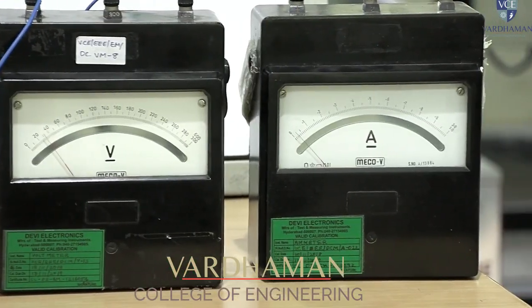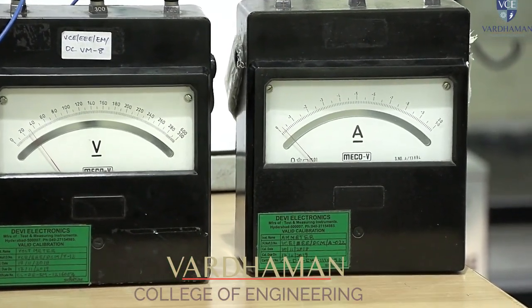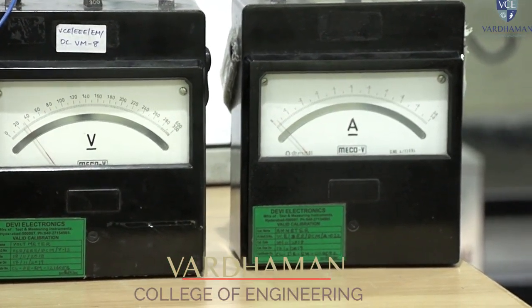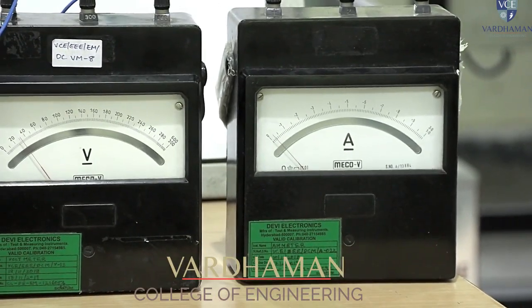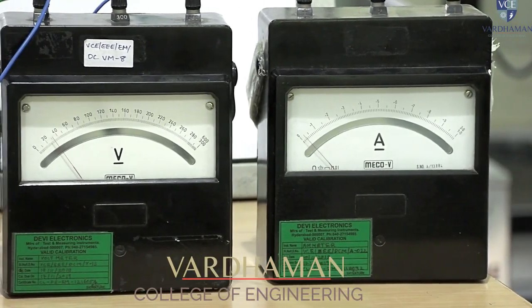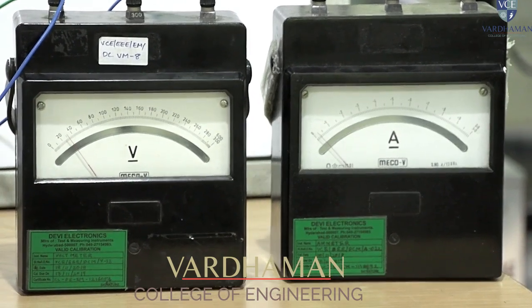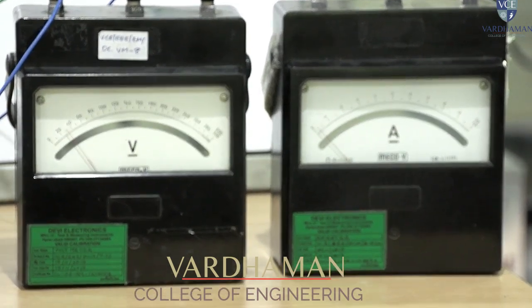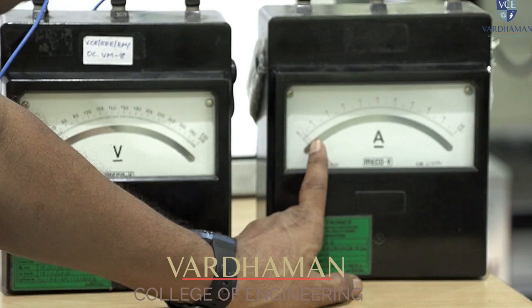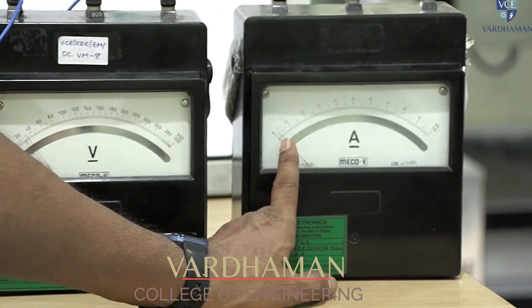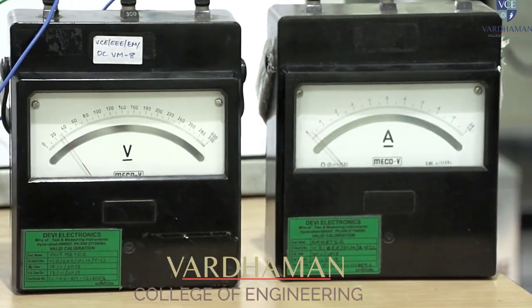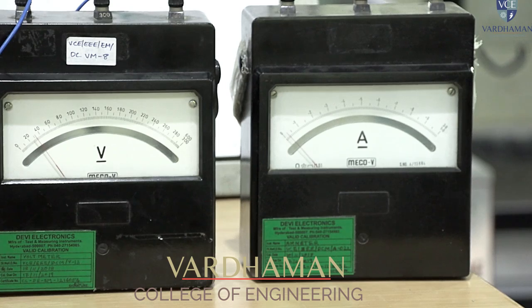This voltage is taken by this wire to the rheostat. The entire resistance is taken and leaves from this black terminal to Z. That means the current flowing through the magnetic field coil is controlled by this rheostat. Your ammeter shows a very negligible current, 0.02. I will vary this current so that the current flowing through the magnetic field increases and the flux increases. As the changing flux increases, the voltage also increases.